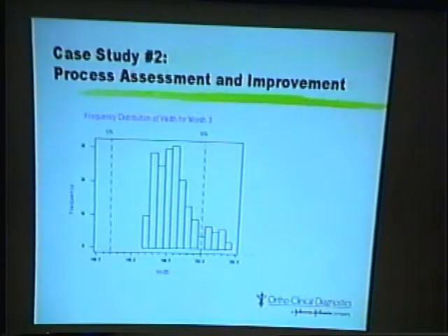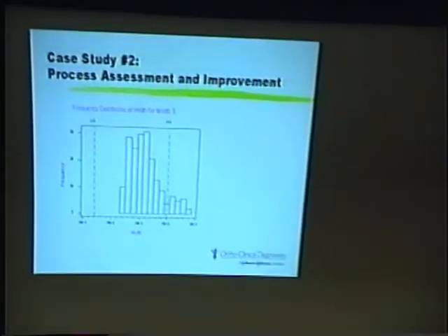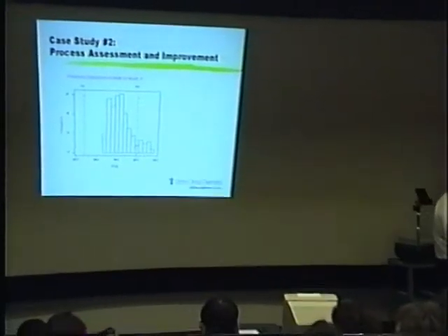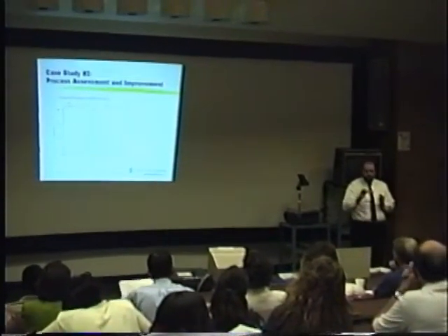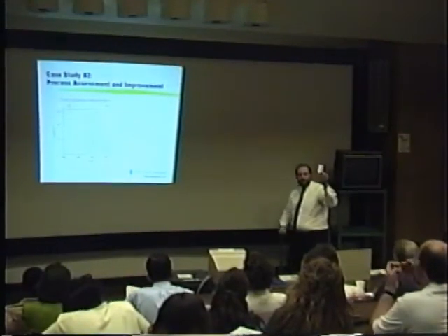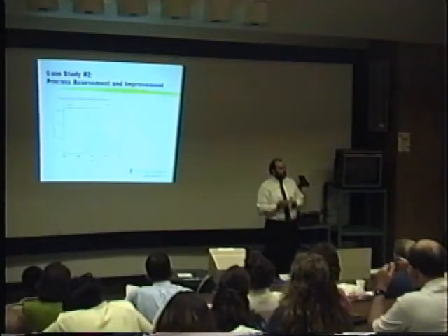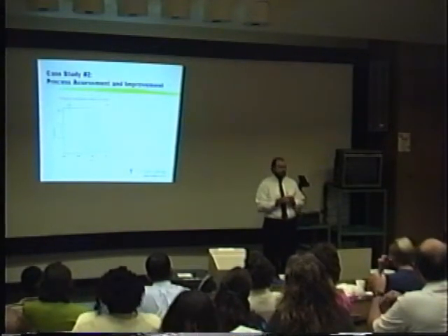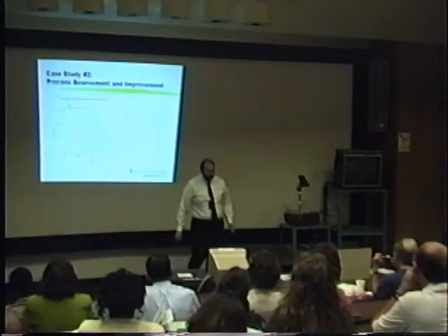In this case, there are 8 of these trays lined up in a grid, and they're punched out at once into a flat sheet, and then a secondary operation comes down and cuts all the cavities apart. For reference purposes, this, for example, is cavity number 7. For troubleshooting, we can go in and say, we know we've got a problem here, could it be cavity related?